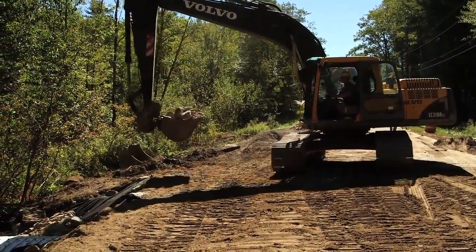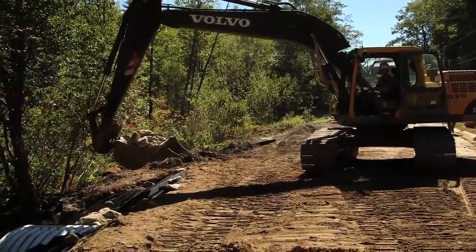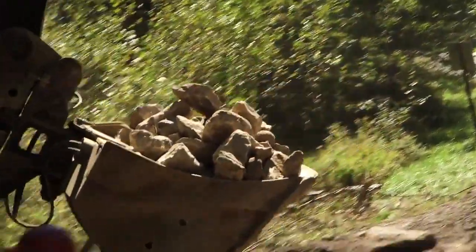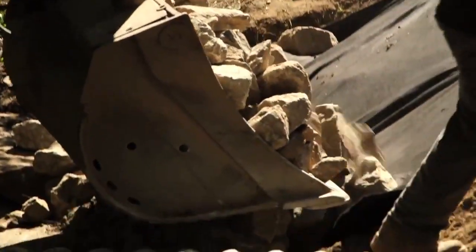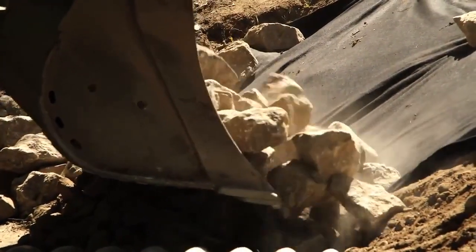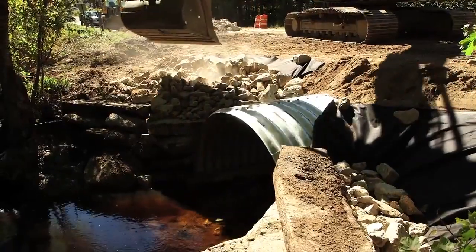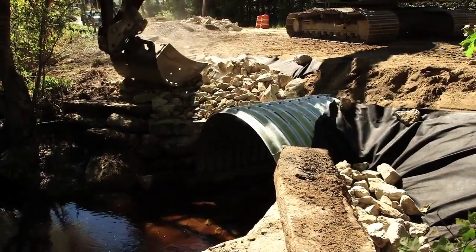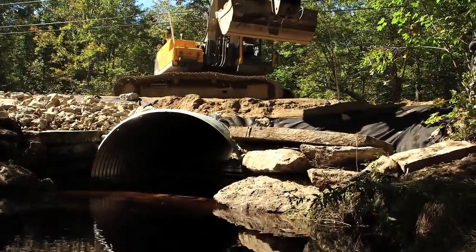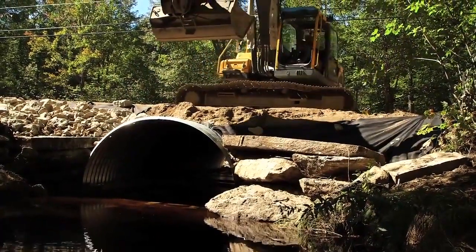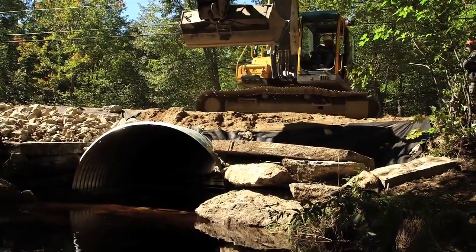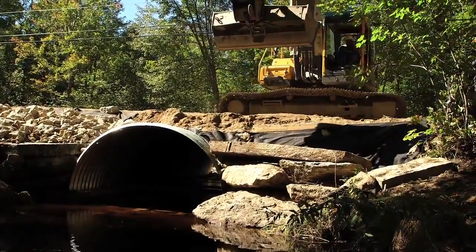The entire surface of the slope on both the upstream and downstream ends of the culvert is armored with either the old stone blocks from the previous pipe or new riprap. This reduces erosion potential of any of the compacted gravel fill during high flow events. If the opening for the culvert is properly sized, sediments will typically be deposited upstream, downstream, and under the culvert to form a continuous natural low-flow channel.